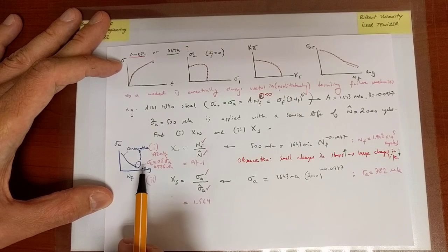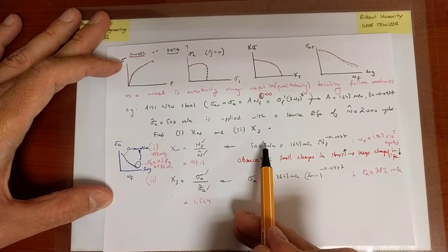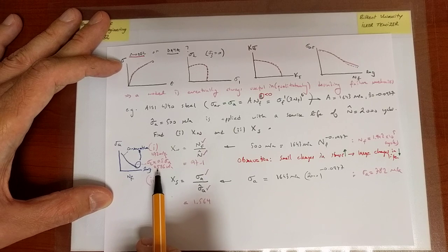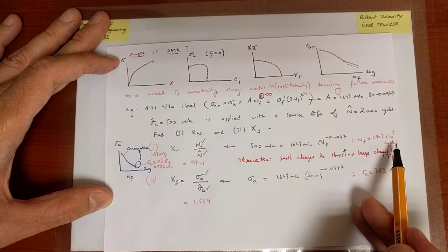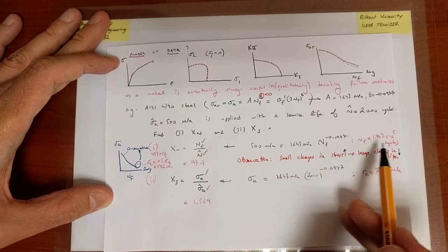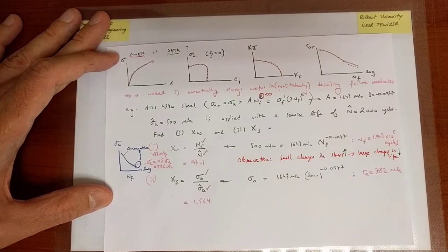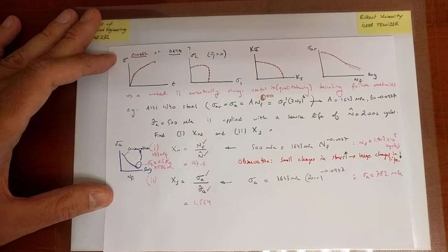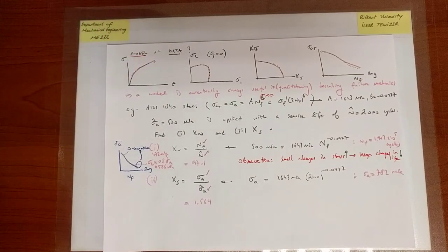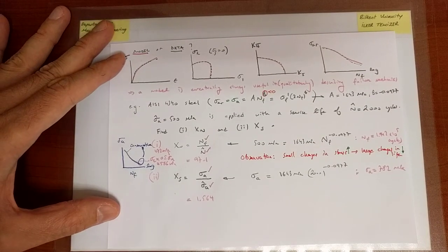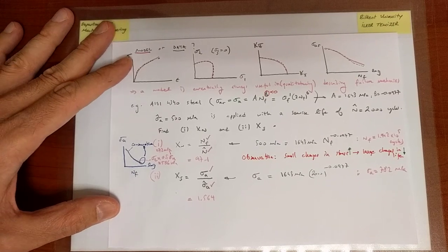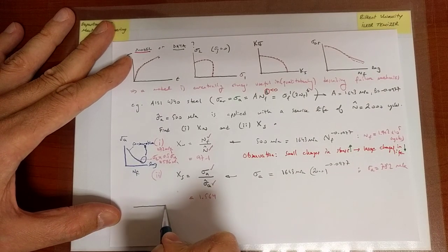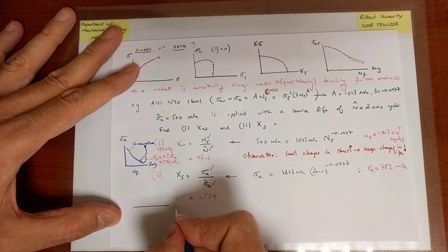And in particular here, because this value that we're applying, 500 MPa, is below the endurance limit, probably we're going to be able to cycle for much longer. But still, we are presently omitting that and going for a conservative estimate and estimating the safety factor as such. Now, having said all of this, let me quickly summarize some of the current limitations beyond which our following discussions will go.